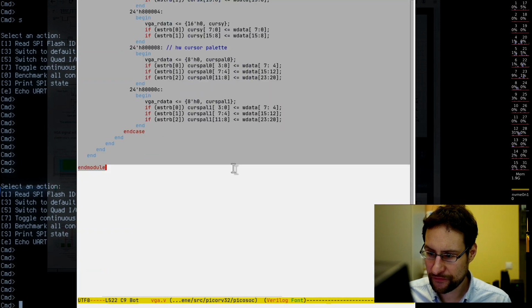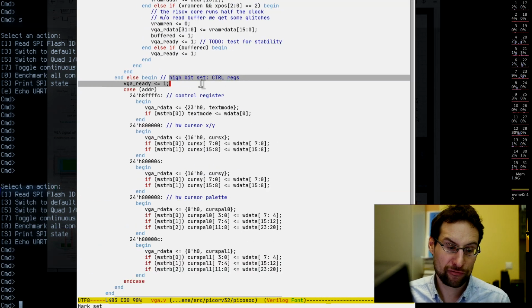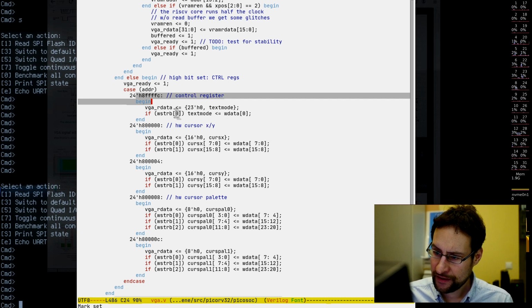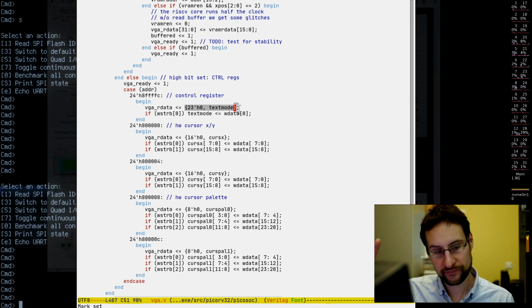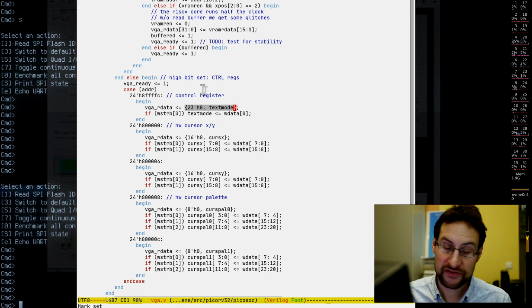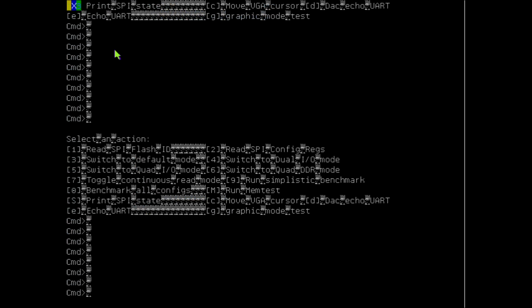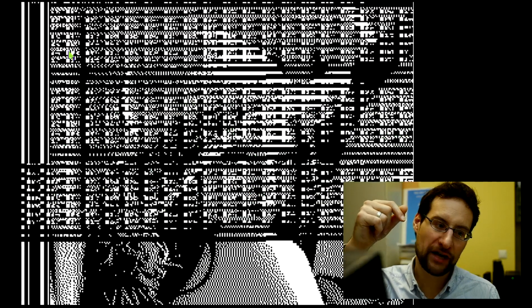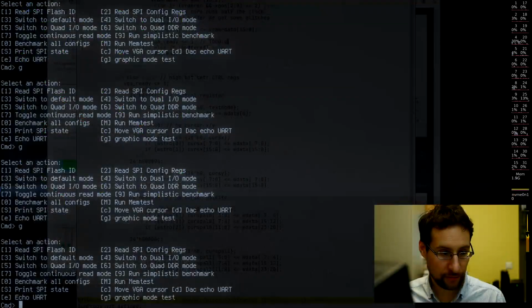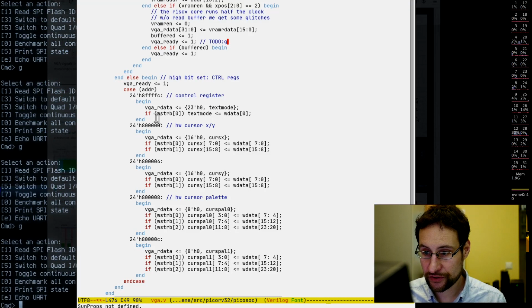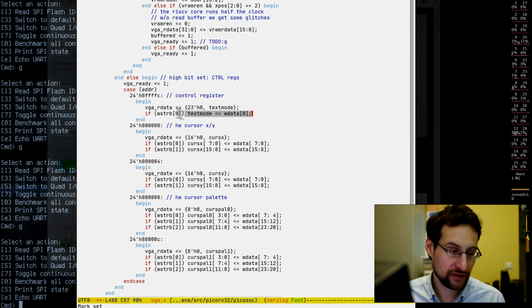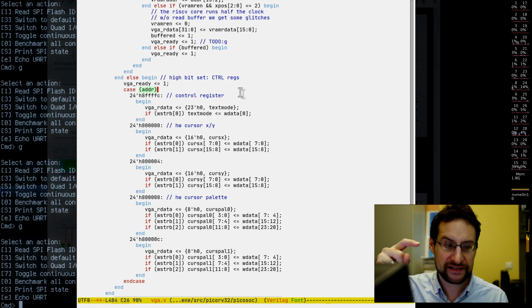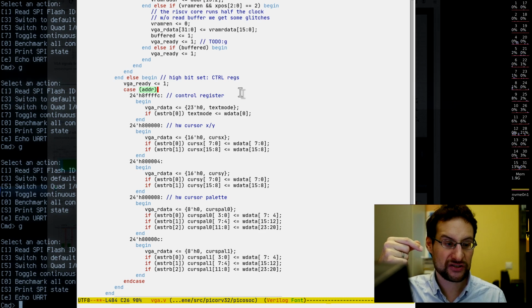And then the rest of the file is only the control register decoding. So we have here the very highest bit of the address range, like FFFF is text mode. The first bit in the highest address space there is toggling between graphic and text mode. That looks like that. So this is just one bit from the RISC-V CPU writing to this control register, copies this one bit, assigns this to the text mode here. As you see, write data first bit, assigning this here to the text mode, and this makes the output instantly toggle at the next pixel clock cycle. It will instantly